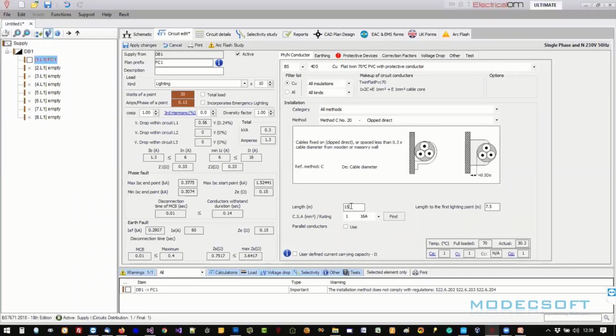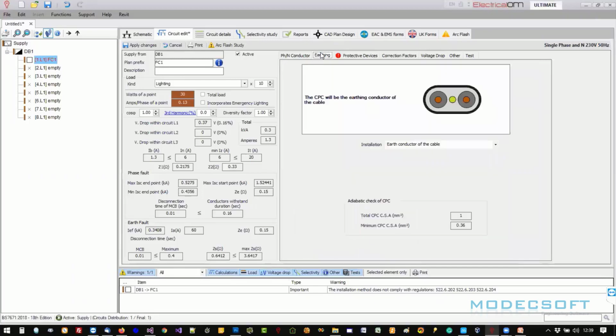So you know the factors involved in that resistance measurement, so you can reverse engineer that logic and get the length of that cable. And this is something you are doing to make sure that the test results versus the design results are correct. Okay, so I'm just going to leave that at 15 at the moment. This is a 1.5 integral conductor, that's fine.